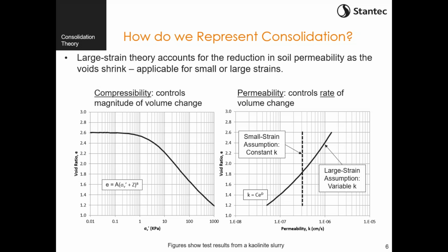So it's a seepage-induced stress, and by doing that, we can evaluate our compressibility at low effective stresses. For a slurry, that's important because in an extremely large impoundment, capturing the volume change at these low stresses could have a fairly large impact on our overall calculation results. The second thing that the seepage-induced consolidation test does is it directly measures the permeability during the test, so we can evaluate this relationship between permeability and void ratio.